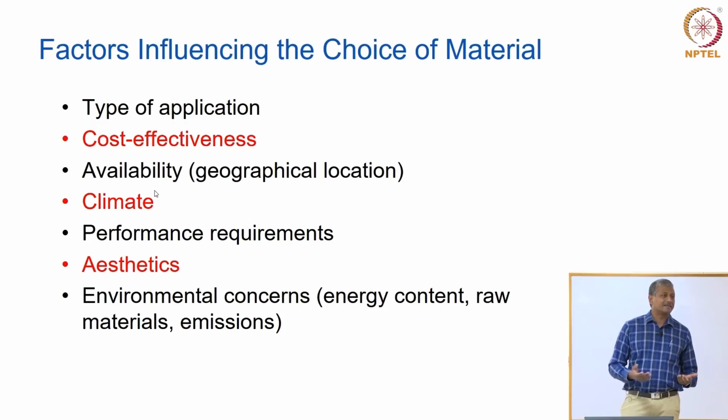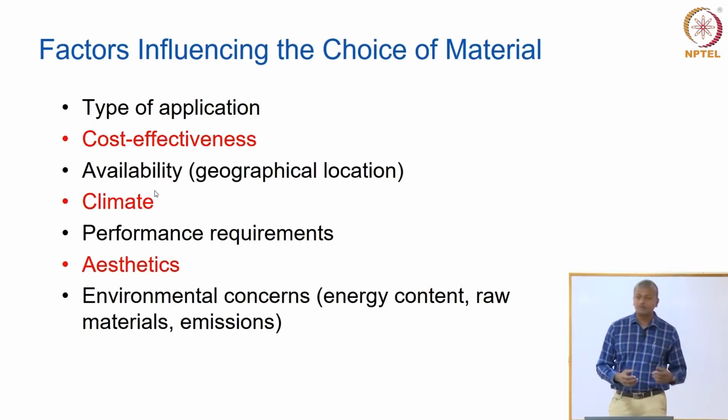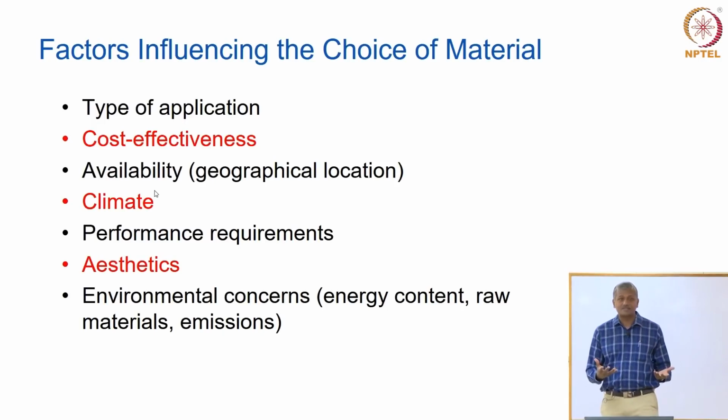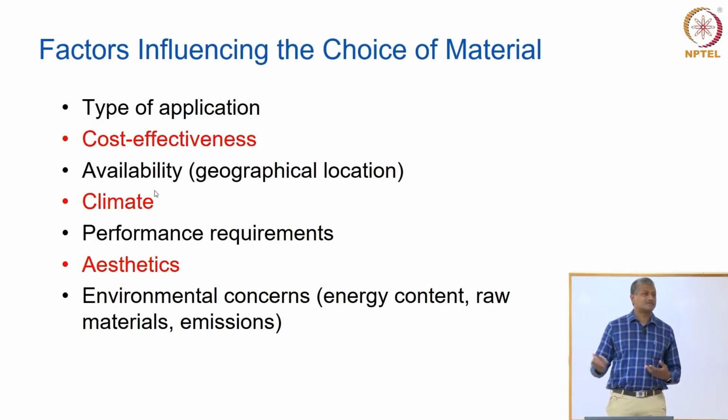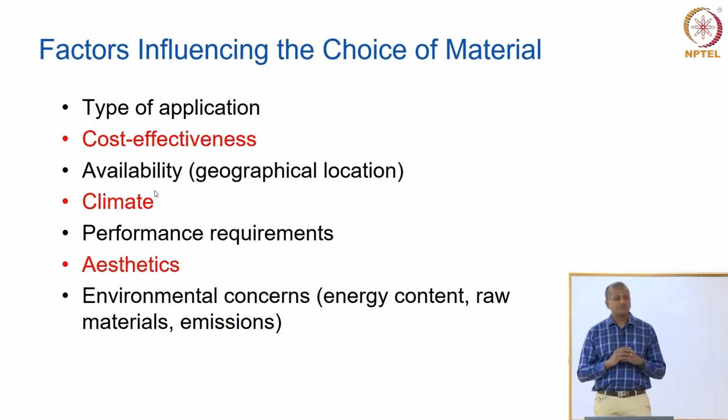Of course, in certain areas, the climate will govern the choice of a material. For example, if you go to the northern European countries where very little daylight is available most of the time, you could use glass as one of the major materials of construction because it allows in a lot more light. But unfortunately, in India also, we started copying the Western use of glass, and most of our IT buildings and structures have also come up with these glass facades that are completely enveloping the building.